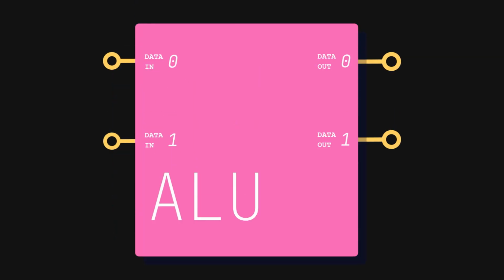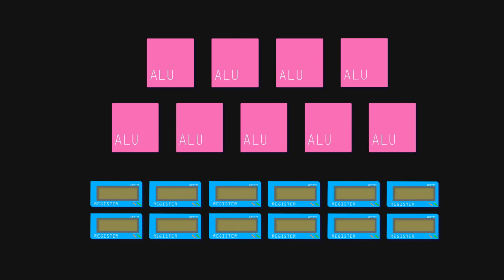We keep the ALUs. They can do the usual ALU stuff: addition, multiplication, bit shift, etc. The registers can be read by and written to by any ALU and will serve as the main form of communication between them. The idea is that the registers store data. The ALUs operate on that data. Having a register bank instead of simple, anonymous buses is important because it will give us the power to manage the data going around manually.